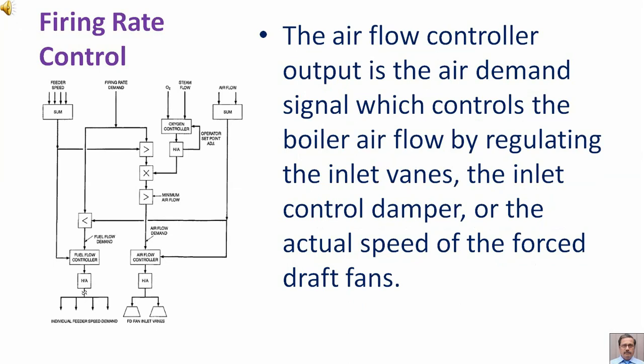The airflow controller output is the air demand signal, which controls the boiler airflow by regulating the inlet vanes, the inlet control damper, or the actual speed of the forced draft fans.